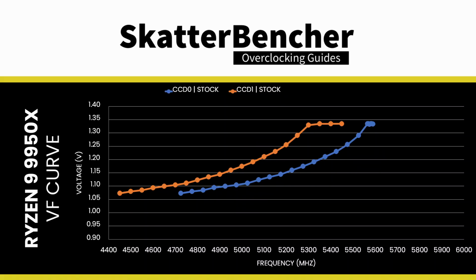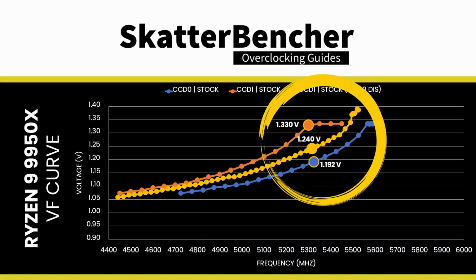I must make an important side note here. The native VF curve for CCD1 is not as bad as it is portrayed in this chart. Instead, it is the effect of the CCDs sharing the same voltage rail and having linked Fmax frequencies. If we disable CCD0 and reassess the VF curve of CCD1, we find that CCD1 is able to run the high frequencies at much lower voltages. At 5.3 GHz, we even need about 100 mV less. Of course, CCD1 is still not at the same level as CCD0.